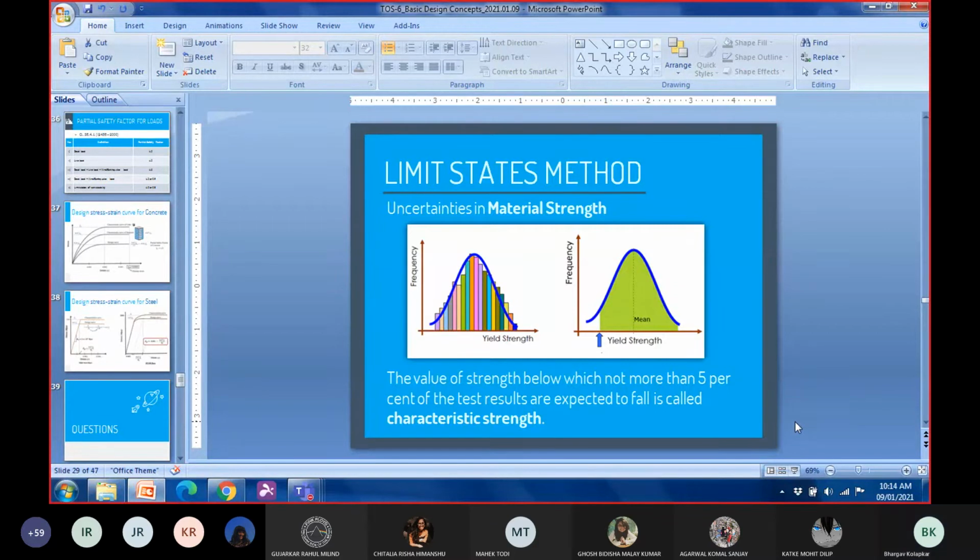Yeah. So basically, it's just the passing percentage. 40 megapascal, 40 is the passing percentage. Now, why is it that we select a lower value and not a higher value? I've said this time and again. Every time we underestimate strength and overestimate the demand.